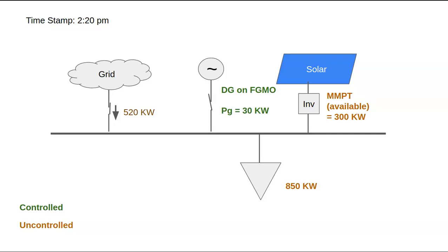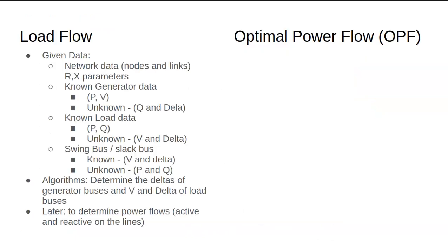So this grid is the swing bus. That's why this 520, whether 550, whatever case, 180, P can be plus or minus whatever. It is possible because the grid is considered as a swing bus. You cannot define all P's. If you define all P's, then the addition of the P supply and the addition of the P demand may not match. So in order for that, one has to be there. Of course, multiple swing buses are also possible. First let us discuss the basics, then the advanced.